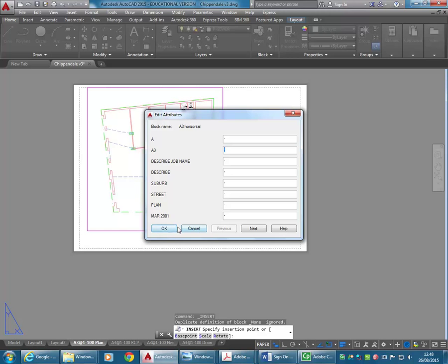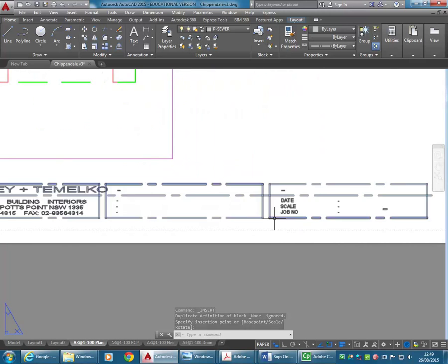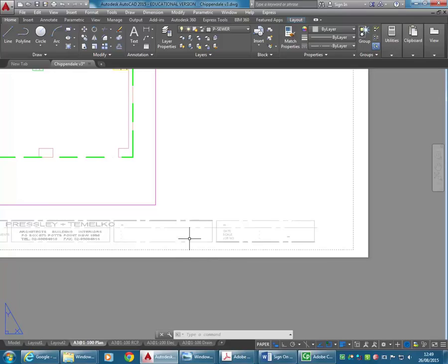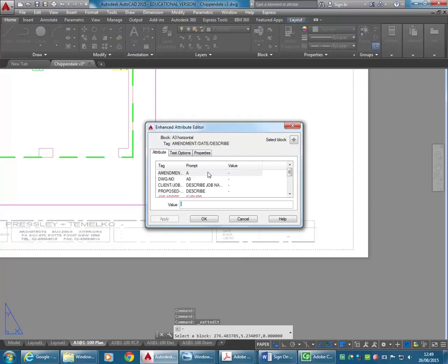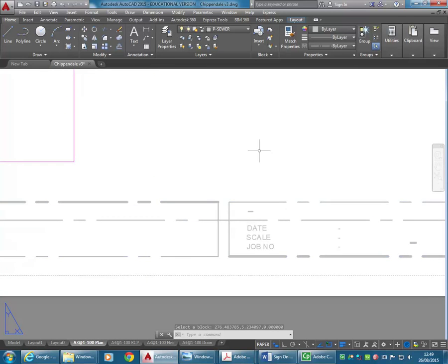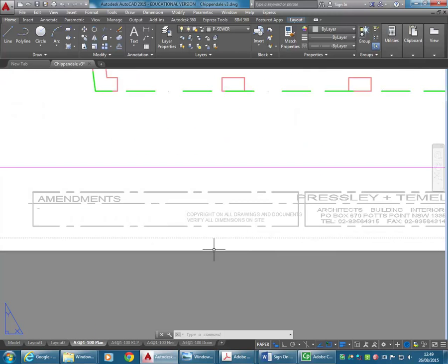Now look, okay, I'm just going to leave it actually because I was going to show you can modify it, but instead we'll just use it as a reference because you need to know how attributes work, and that's something, if we get time I will show you later. Attributes aren't that hard, and that will give you basically adjustable fields in a block, which makes sense for something like a title block. You can then just go through and put in your own values rather than modifying a set of different text objects. But it'll take too long if I do that now. So we'll keep it simple and copy the values they've got here just to give you a good guide.